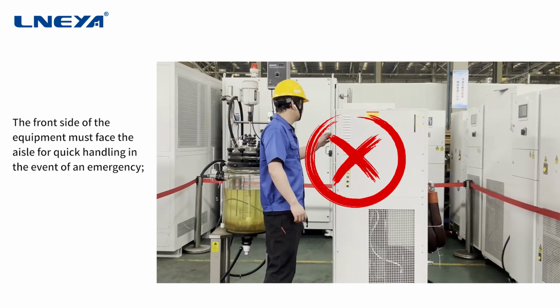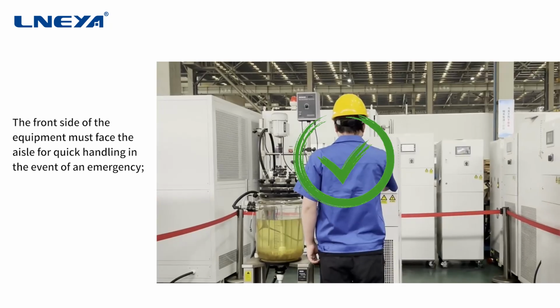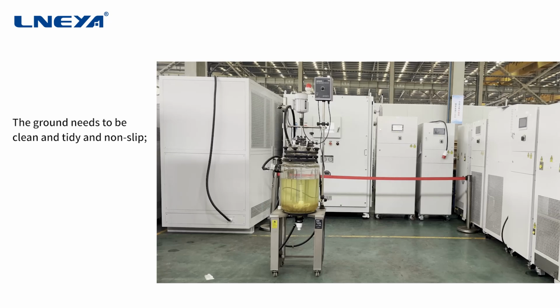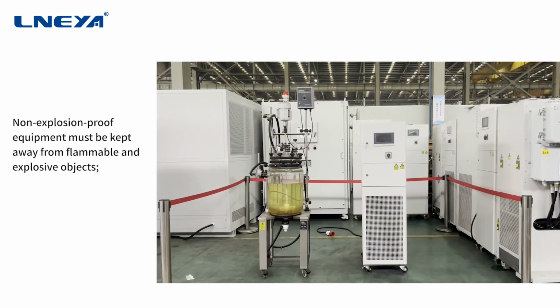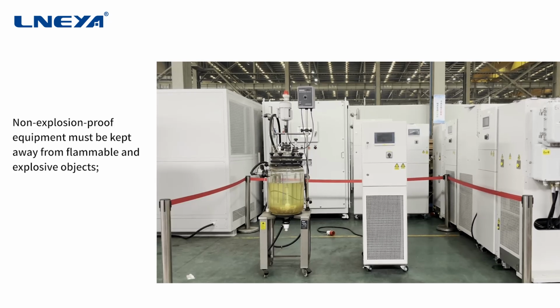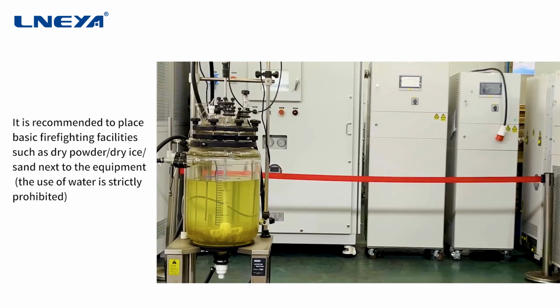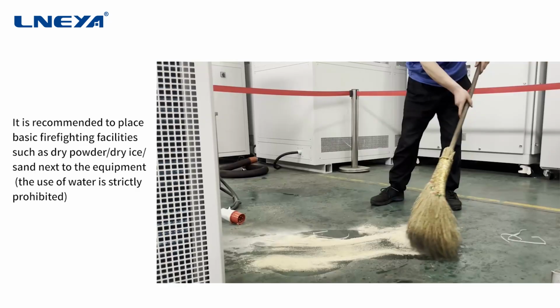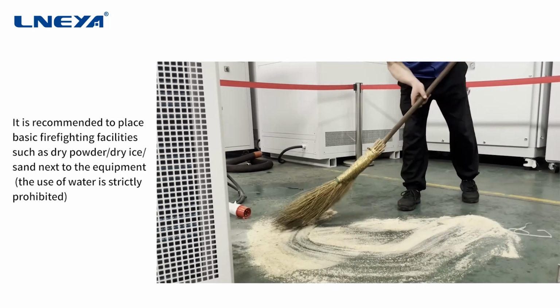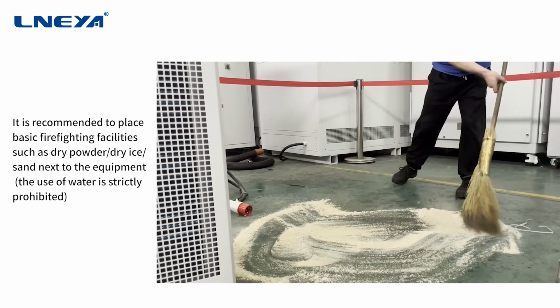The front side of the equipment must face the aisle for quick handling in the event of an emergency. The ground needs to be clean and tidy and non-slip. Non-explosion-proof equipment must be kept away from flammable and explosive objects. It is recommended to place basic firefighting facilities such as dry powder, dry ice, or sand next to the equipment. The use of water is strictly prohibited.